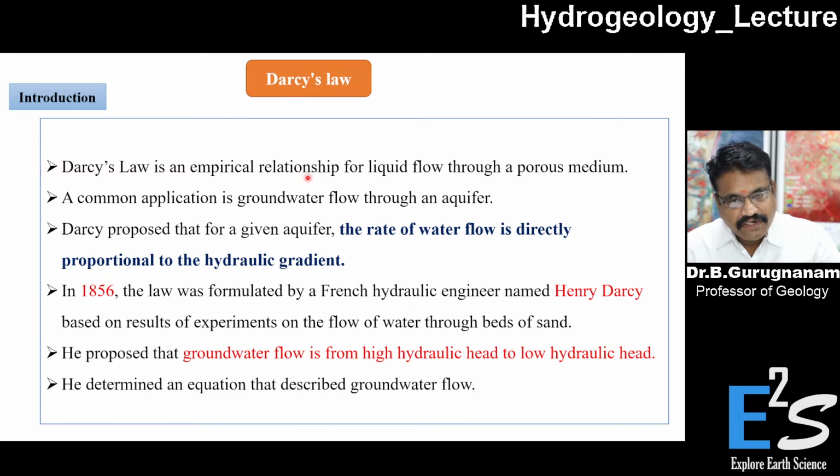It's the relationship between the fluid, water, and how it passes through a porous medium. If the pores are connected with each other, that is called permeability. And Darcy's law reflects the permeability assessment. This is the common application people still use for assessing permeability or the movement of water in the subsurface, in terms of centimeter per second, by means of Darcy's law.